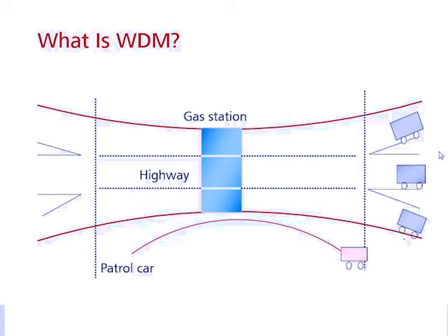In the WDM system, when we access the customer service, if we want to transmit different customer services in the same fiber, the first step is we need to make different customer services carried by different colors. Different colors mean different wavelengths. It means different customer services should be carried by different wavelengths and mixed into the same fiber, and then it can transmit in the WDM network.